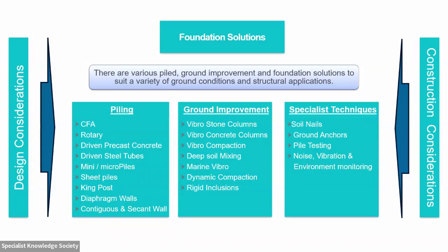I'm going to be covering today, concentrating really on piled foundations, because piled foundations is my background. So I'm going to run through some of the main elements of piled foundations and look at both the design considerations and the construction considerations that feed in to the piled solutions. A lot of piled solutions are covered there in the left-hand box, and they can be split really into two types of piles. You've got displacement piles and you've got replacement piles.